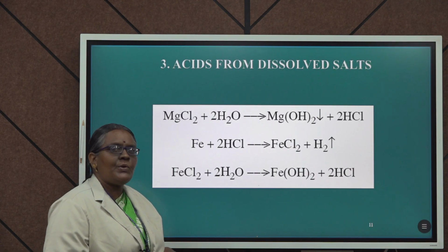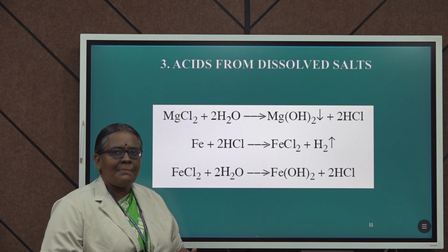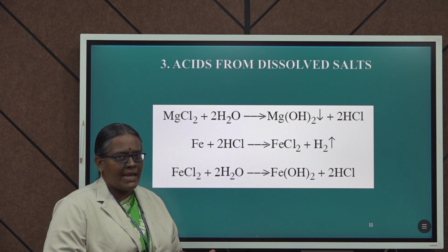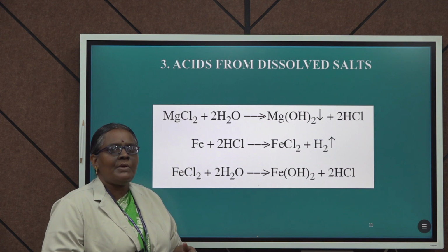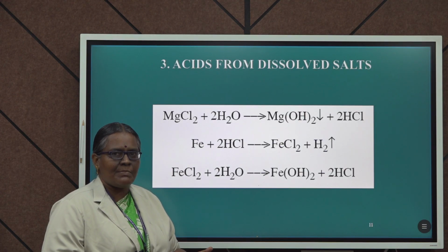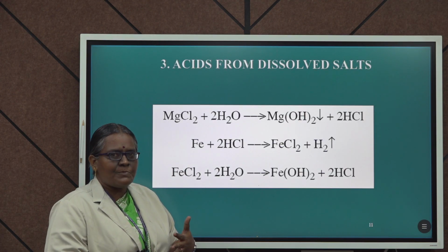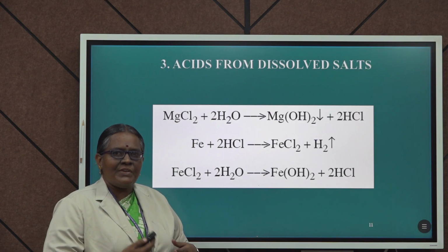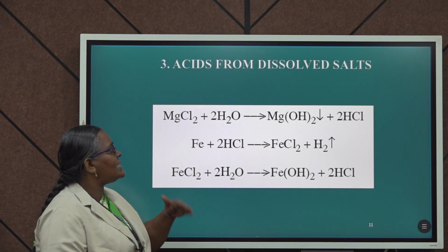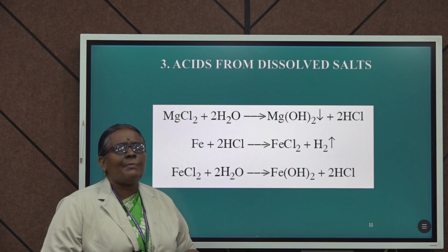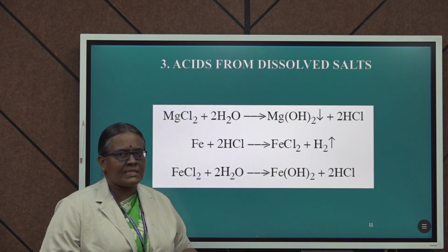This can be removed only by adding some alkaline material like NaOH, but the sodium hydroxide will also result in caustic embrittlement. So, this is a continuous process. Effective softening must be done to remove all these salts so that boiler corrosion can be minimized.